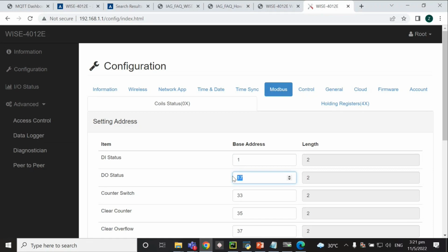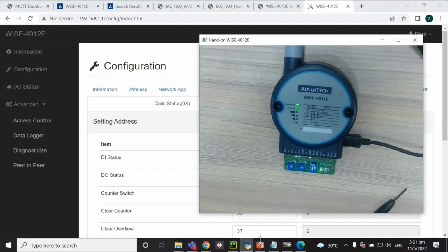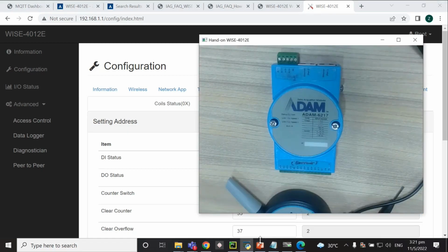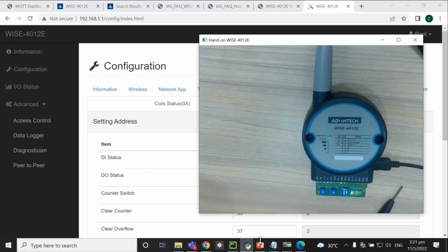Why is our internal firmware defined like that? If you look at our Adam hardware, the maximum channel we design for is 16 channels. Whether the design is input or output, digital input or output, they use a hop of 16 channels, 16 channels, 16 channels, whether you are using them or not.